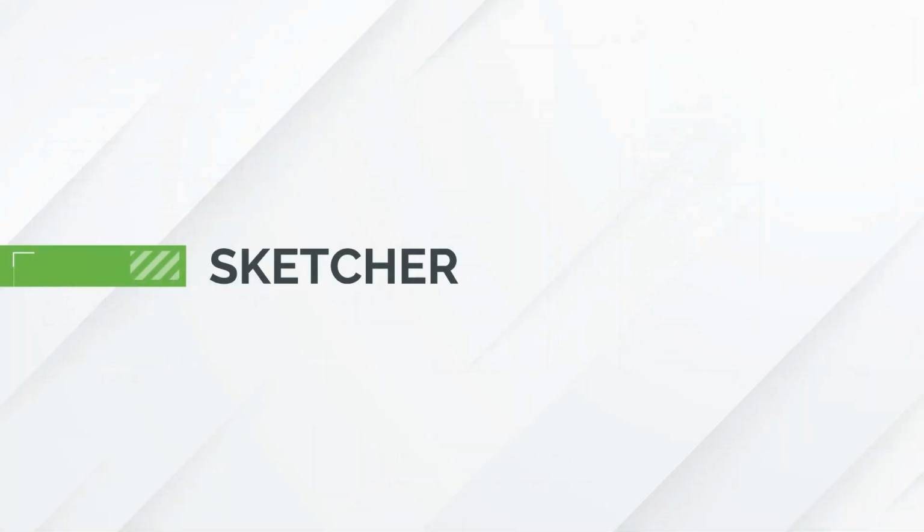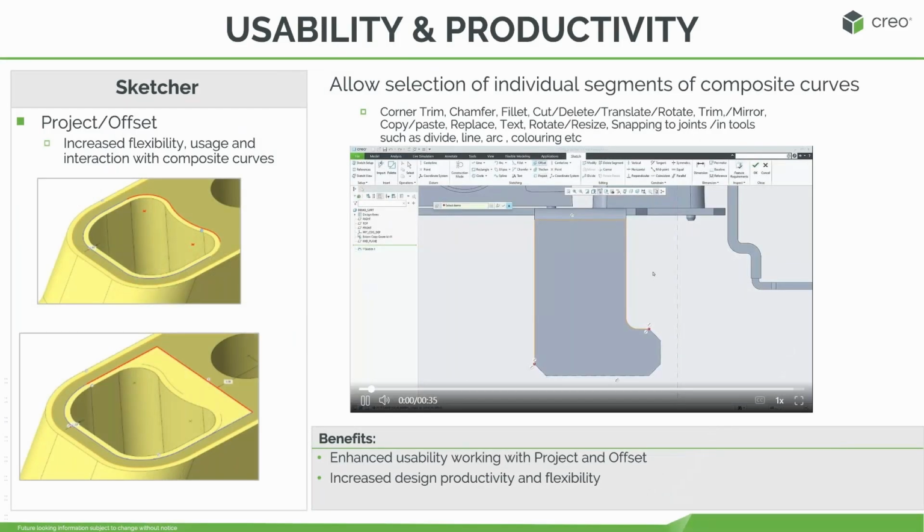Next is Sketcher enhancements. Starting with Creo 9, PTC gave us the project and offset command in Sketcher a modern outlook, bringing them in line with the 3D modeling workflow. So with the new Creo, that's even getting better now. You're no longer limited to working on a whole composite curve. You can now edit an individual segment directly.